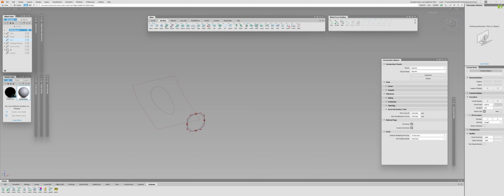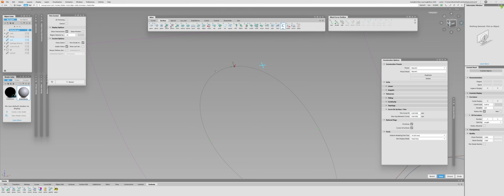Where is the example for that? Oh yeah, here it is. So max gap between curves. Technically, if I zoom into the circle closer and closer, there is a small gap, but intentional. Then I project it using the trim curve fit of 0.001 onto the surface. Now, if I zoom in, you will see that there is a small gap here. With the tight max gap between curves of 0.001, it calculates this distance and says